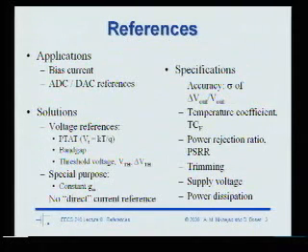So using all the tricks that we use in integrated circuits, like ratios of resistors, it just doesn't help. What you have to do if you need a precise current is to have a precision resistor off-chip, 0.1%, right? You go and take the resistor out of the bucket, and it's a precise resistor and you get a precise current. So that's one thing to keep in mind, because if you can come up with something, boy, that would be great.